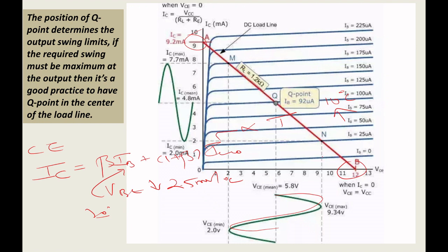That's what I showed. If it moves away from the center, either the positive part or the negative part is clipping. So as an engineer, we want to design a circuit where the quiescent point is stable, and we have to recover the old quiescent point. It should be free from clipping. That is the main reason why you want to study different types of DC biasing circuits.